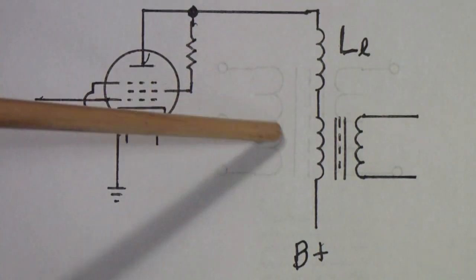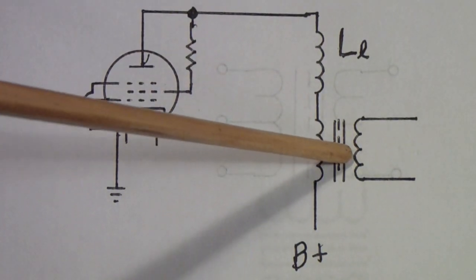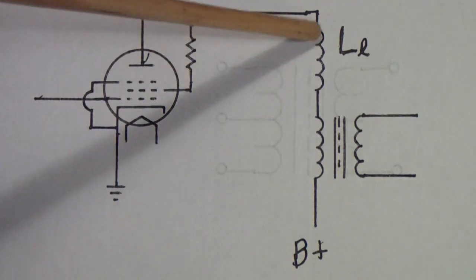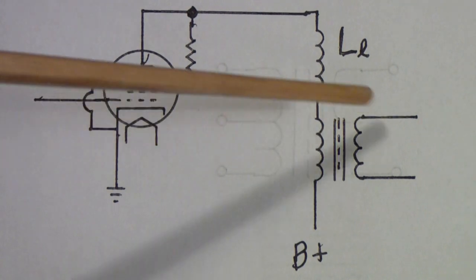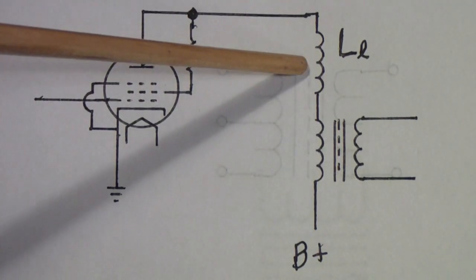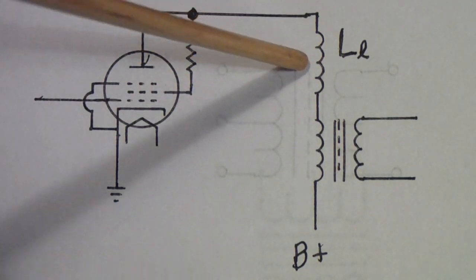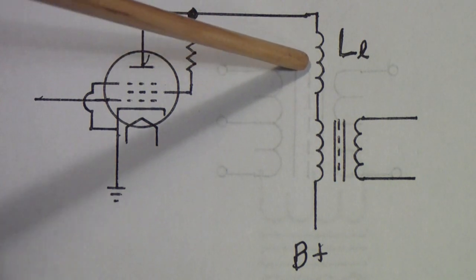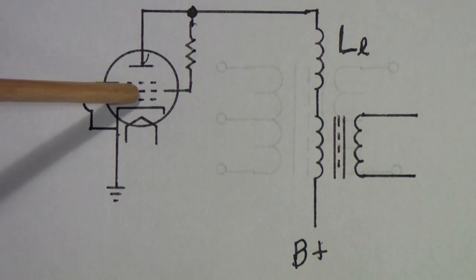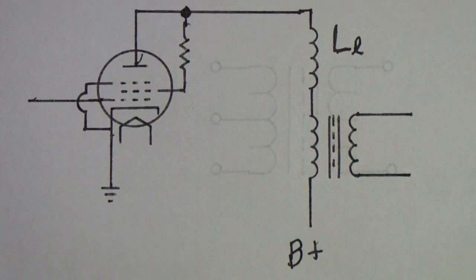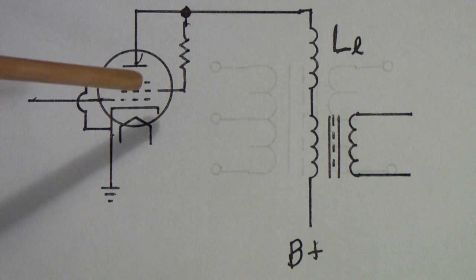And you can determine how bad a particular transformer is going to be with regard to leakage inductance by some measurements that I'll show you in a second. But the important thing about the leakage inductance is it occurs right at the time that the one stage is turning off and the other stage at the bottom, if this were push-pull, is turning on.